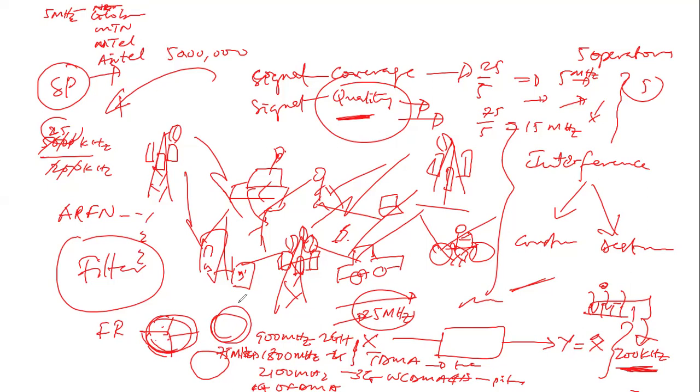So in planning the telecom network, we have to reuse the same set of frequencies, considering interference and all of that. Because we cannot use the same set of frequencies in the same cell. That's why it's cellular, because there will be co-channel interference. When we deal with different frequencies, we begin to deal with adjacent frequency interference. The effect of this is to increase the level of interference in the system on the physical side. This can also degrade your signal, because after all of the signal processing, what we deal with on the electronic side of the process is noise, not interference. There's a big difference between noise and interference, isn't it?